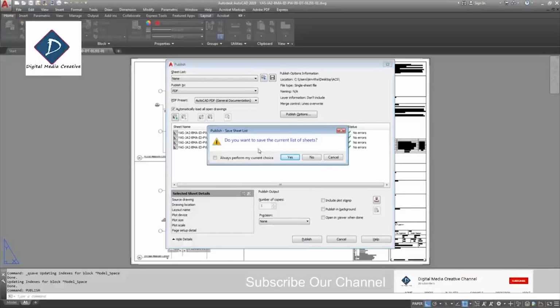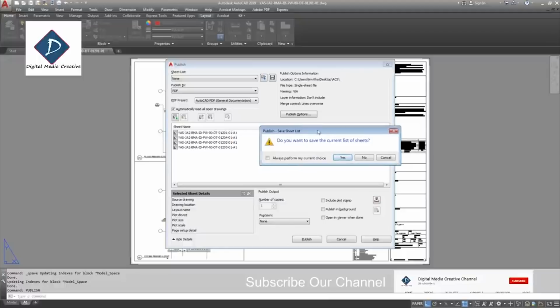Then it's asking to save the setting. The thing is, this is only for the list. So if we save it, for example, you have to export the PDF, DWF and printing, but it's the same set of drawings. So what you can do, just save, then you will get the same setting from using here in the sheet list. So I'll show you the example if you want.